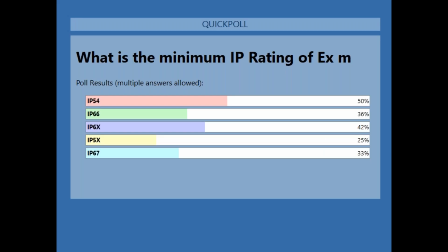Okay, so the correct answer is, for cable gland entry into any device, 60079-0, Annex A3, minimum IP ratings for EPL Ma or EPL Mb and Gs is IP54. But you have to use a sealing means, an IP washer, during testing to prove IP54.